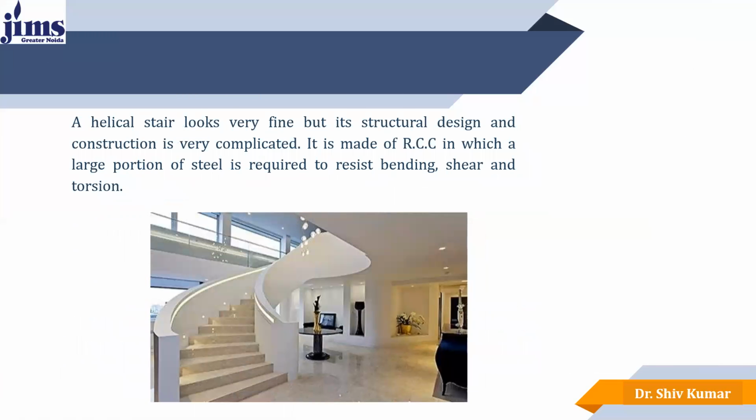The next is the helical stairs. It looks very fine, it looks very beautiful, but as far as its beauty is concerned, the structural design is very complicated. So it is made of RCC, in which a large portion of steel is required to resist bending, shear and torsion. Sometimes it may fail. So it is really very complicated, so it is not preferred in most of the buildings.